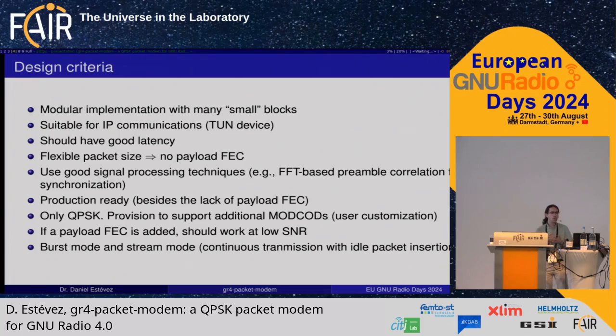And the modem should also support in the transmitter 2 different modes. The first is burst mode. That's when I have 1 packet to send, I send it. If I don't have anything to send, radio silence. And also stream mode, which basically emulates how DVB-S2 and similar protocols work, which is whenever I have a packet to send, I send it. Whenever I have nothing, I keep my carrier, I keep my transmission, I keep sending idle frames. And that introduces considerations for latency.